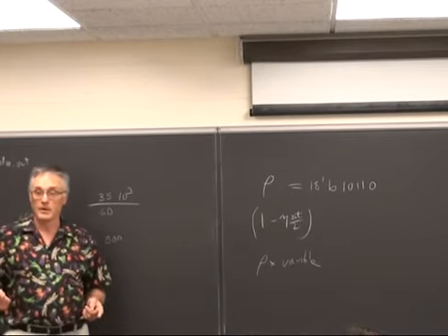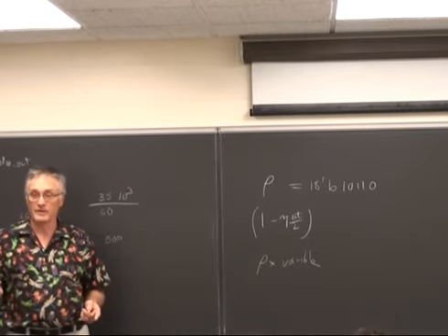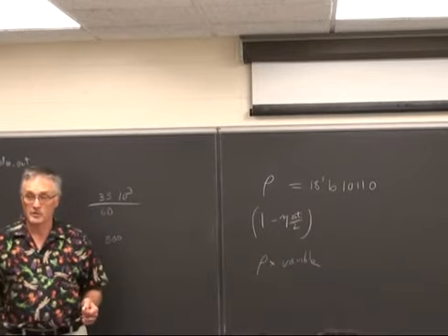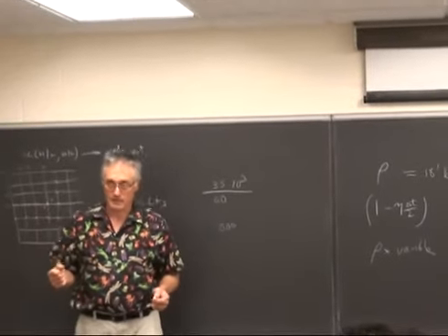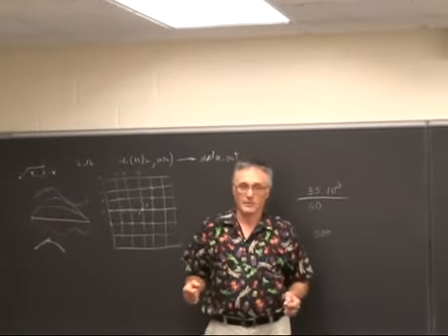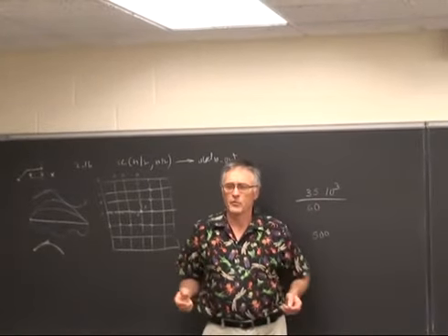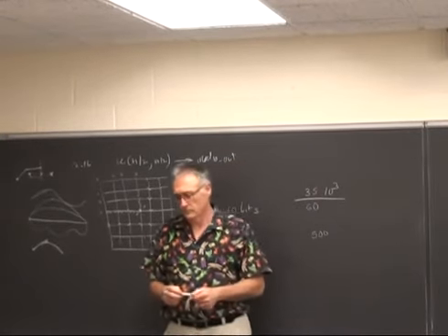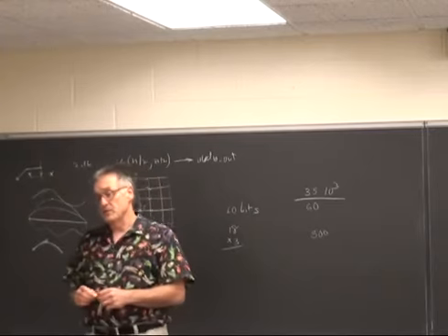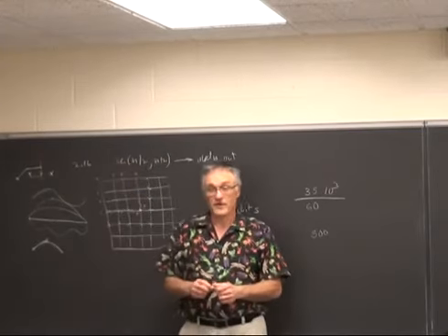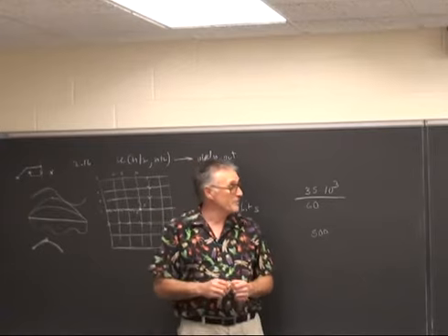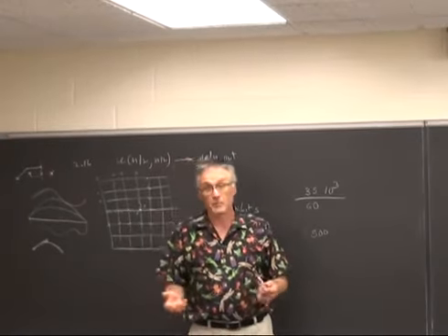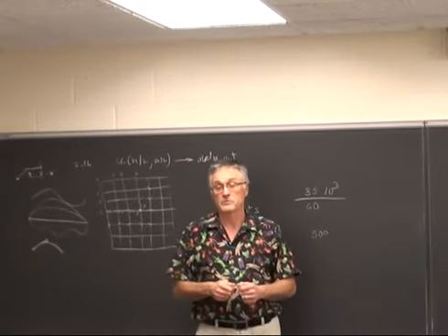But if you use multipliers, you only have 35 18-bit multipliers, unless you use the DE2115 board, in which case you have 480 18-bit multipliers, or some huge number. I think it's 480. But 35 state machines running at full speed should be enough to do something like a couple of thousand computational nodes.